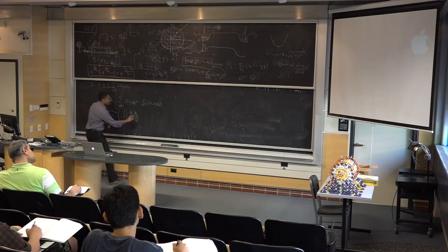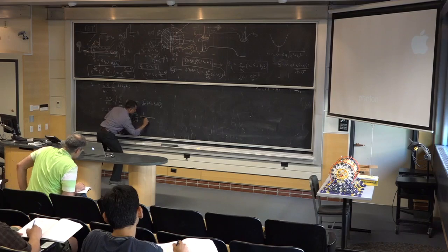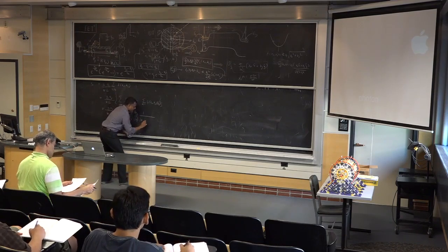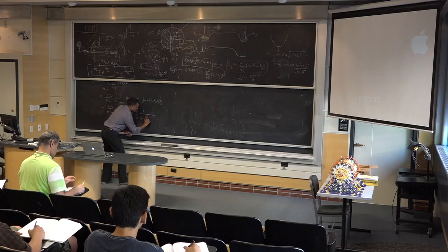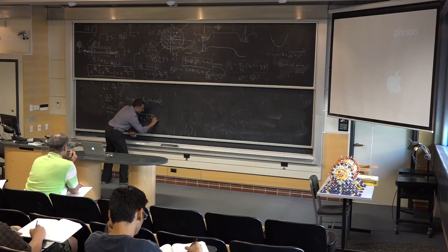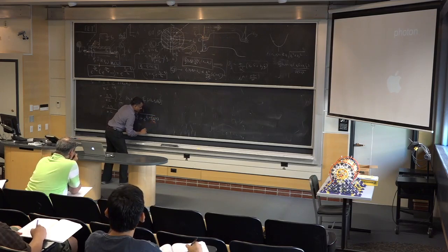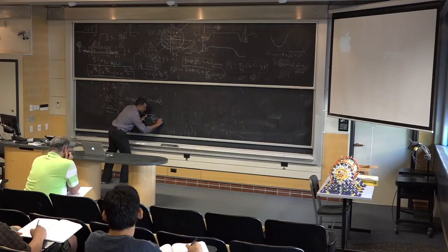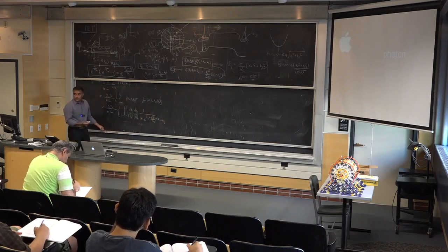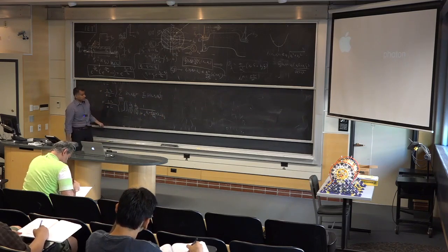And then what you have here is Fermi-Dirac distribution. I'll write the first term in its full-blown thing, and the second term I'll skip. So I'll get EC plus H square, kx squared plus ky squared over 2 times effective mass of conduction band. That's the total energy of the electron minus the Fermi level of the source. That's the first term. Right-going carriers are in equilibrium with the source. Right?